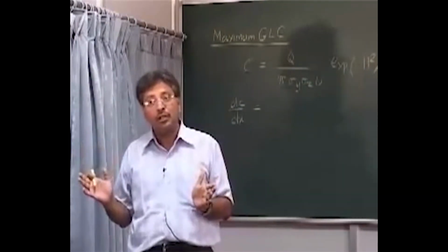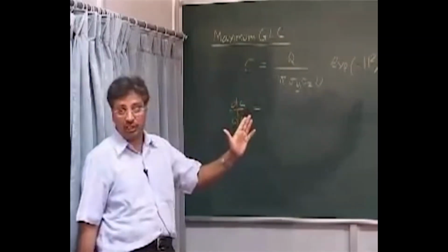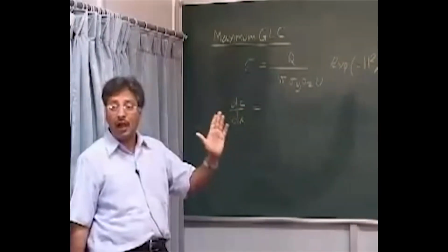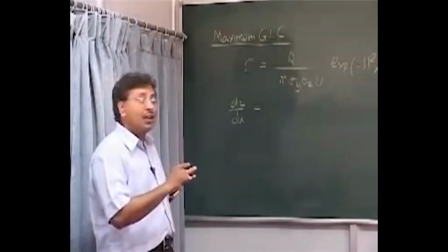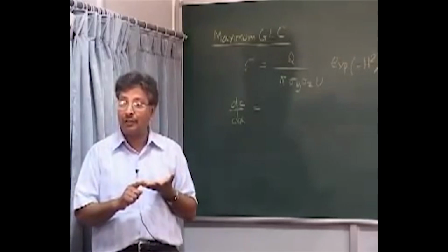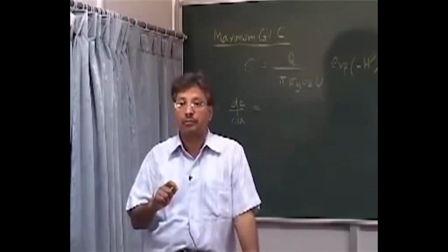You cannot do that. If you want to compute hourly changing concentration, you have to consider the hourly change in the stability, hourly change in the wind speed, and hourly change in the effective height. Nobody can predict what the condition will be 1 hour after this time.